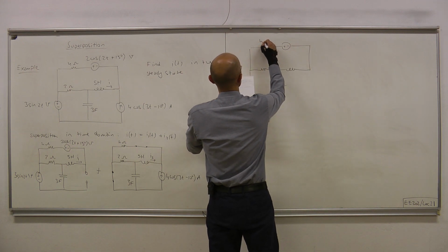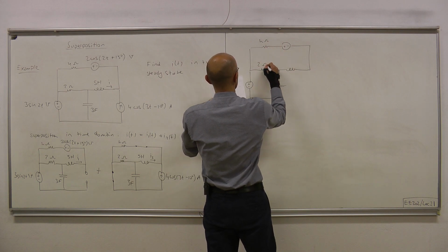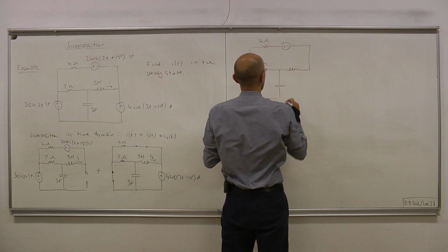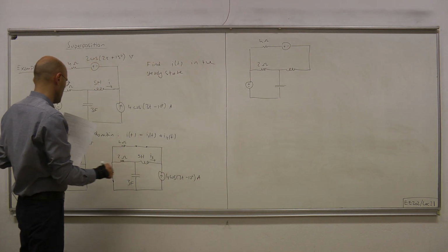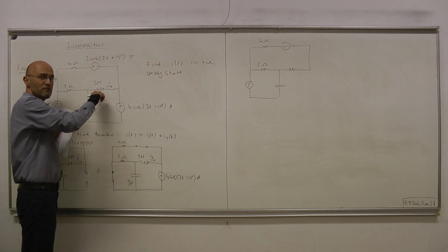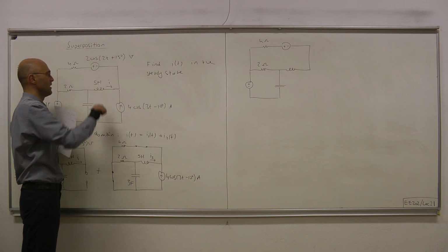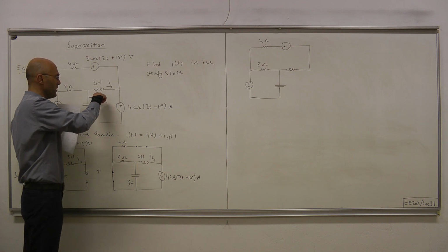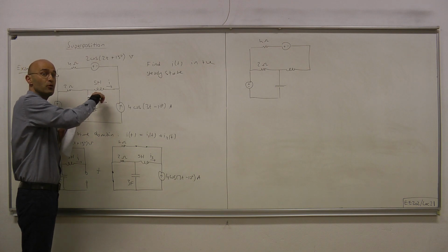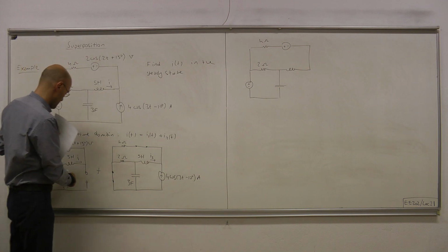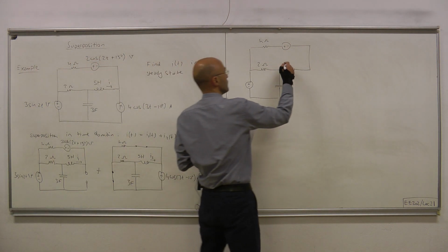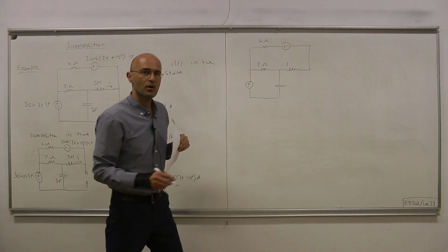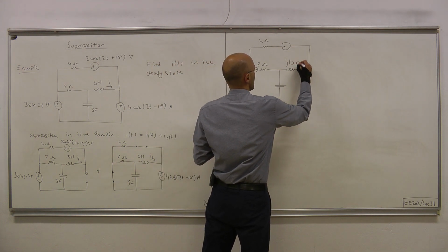Plus minus 4 ohm, 2 ohms. Okay. And now how about the impedances of the inductor and the capacitor? Note that we don't run into the problem that we ran into at the beginning, which was whether the impedance of this guy will be J10 or J15. Now we have just a single frequency, 2, therefore the impedance of the inductor will be J omega L, omega being 2, therefore we have J10 ohms.